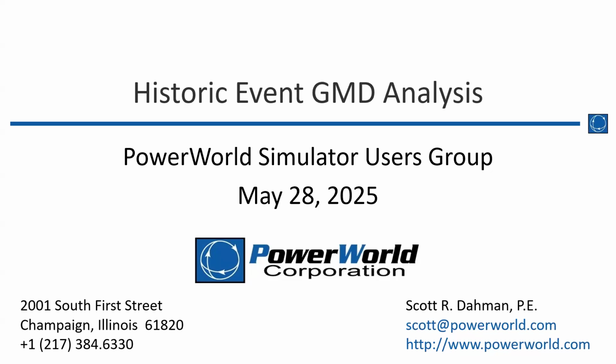I wanted to show where we have a repository of events from the NOAA SWPC that are just in our format, in our PowerWorld Simulator binary format for GMD events, ready to be loaded directly into PowerWorld Simulator. And the other thing that we've introduced relatively recently in PowerWorld Simulator is the ability to load a set of time points from the GMD tool into the Timestep simulation tool for doing power flow analysis. So that's a little bit of a new element here.